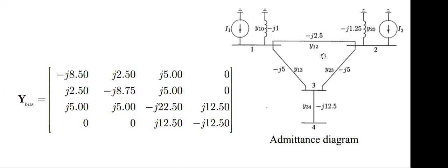Impedance will be given, or it may not be given; there may be other information like voltage or capacity. Then you have to generate the per unit diagram from the single line diagram. That's the first thing.